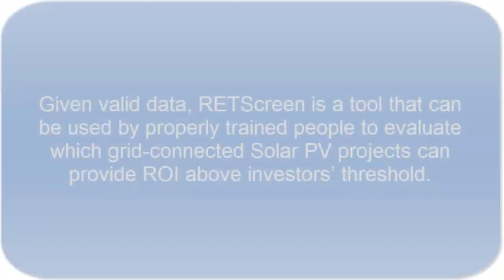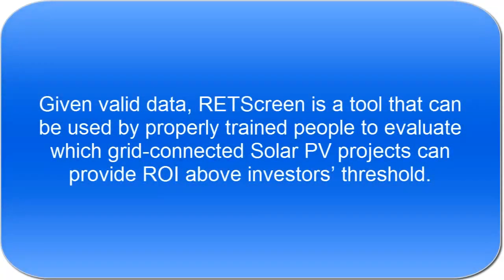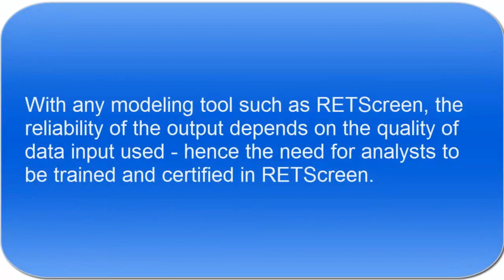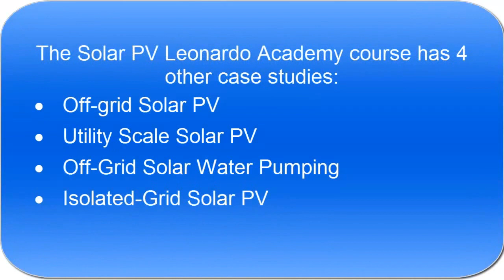It is important to note that the RETScreen PV model was initially designed for off-grid and commercial or large-scale utility projects and is not optimized to take into account important aspects of a net metering project. As such, the model does not take into account the favorable fact that electricity is exported to the grid during peak hours when rates are the highest. For this reason, real-world economic performance is expected to be better than what is calculated by the RETScreen model.